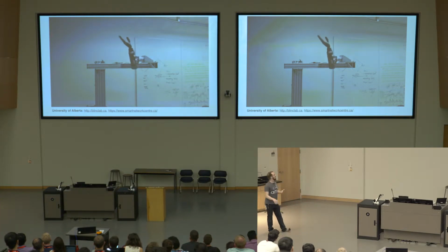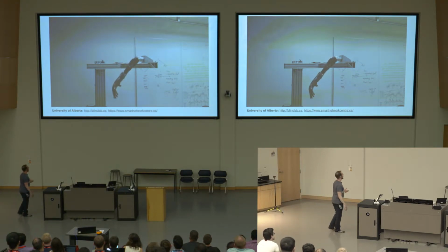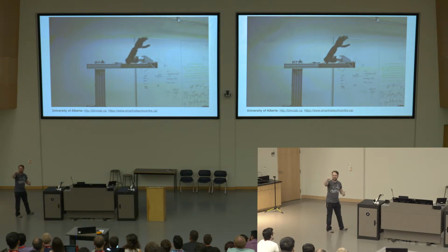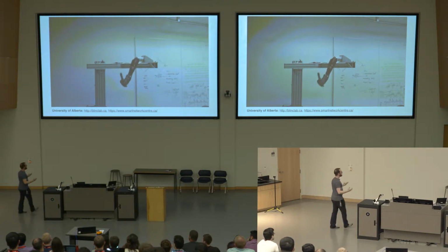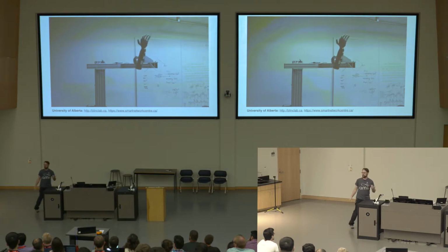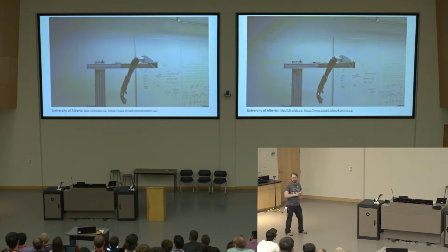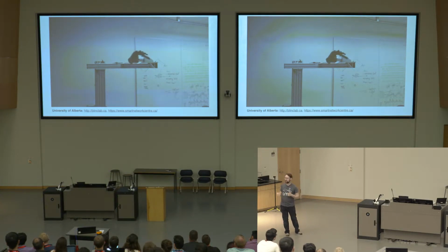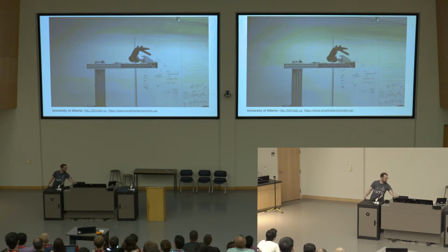but you can't really argue that this arm can't do, to a first approximation, many of the motions that you might expect from a biological human arm. It'll do little finger wiggles, and it can pinch things, and it almost has lumbricals and interossei, like all these different muscle groups are represented by the actuators of a system like this. It's got over 100 different sensors, it's got 17 to 22, depending on the version, controllable degrees of freedom. It's a complicated robot system.